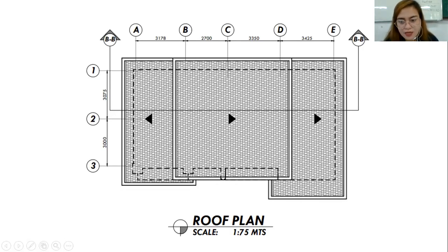There is a question, I think yesterday, it was brought up na how wide is the overhang? So basically, the minimum width of the overhang is 0.7, or that ranges to 0.7 to the maximum 1.5. So normally we're using 1.2 meters for the overhang. That is sufficient na to cover certain area or a certain shade on your wall or on your opening.